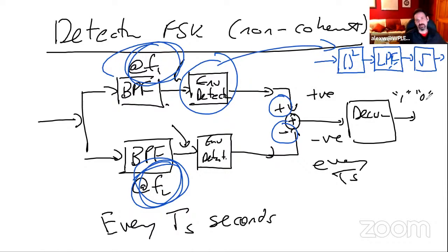I just wanted to go over that because, first of all, I ran out of time and I was kind of fumbling through. But this is how detection for FSK works. In the case of non-coherent detection, you extract out, right? And here too, you can either play at passband, or you can demodulate down to baseband or some signal in between, but you have to know where F1 and F2 are in order to pull this off. Because ultimately what you need to do is bandpass filter out that signal, envelope detect to give you a constant, and put it through the decision-making device. All right? Okay.